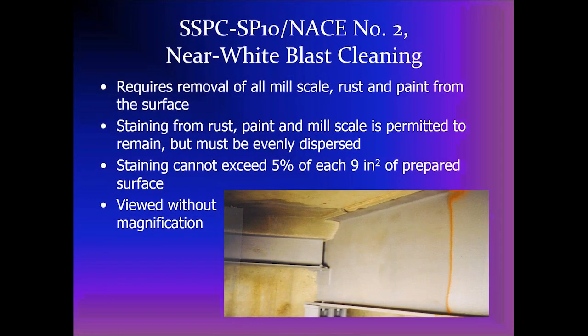Near white blast, SP10 or NACE 2, is basically the same definition as commercial, except that staining cannot exceed 5% of each 9 square inches of surface. The rest is the same. All rust, mill scale, and paint are removed.